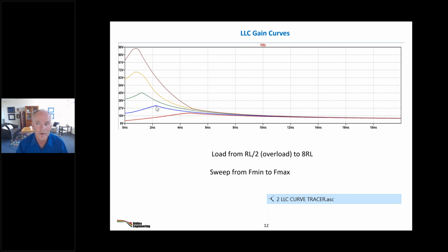Because you've got no controllability at that point. So you back off a little bit. And I remember a number from Hamish Laird one time. It's about a 30% back off. But this is your design freedom. How close do you go to the limits? Because you've got to leave some space there for high temperatures. You've got to leave, what is your true low line? So you design so you're going to be above this resonance, but you've got to have some controllability in here.